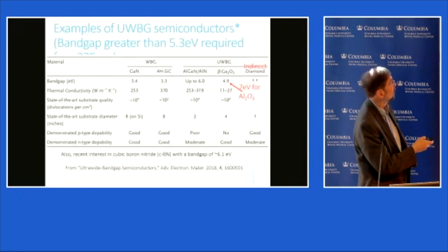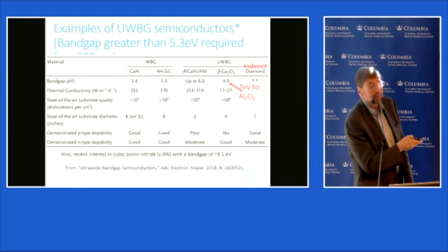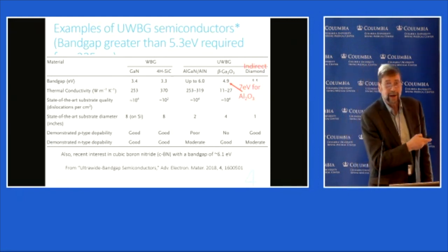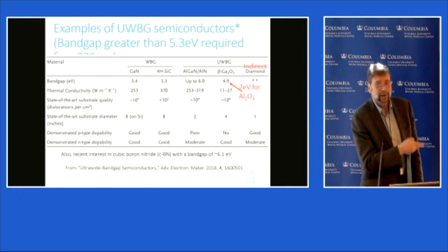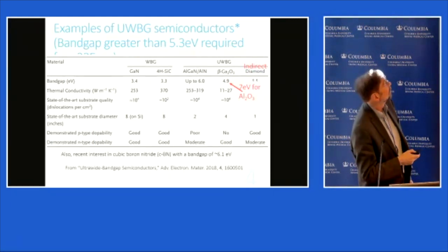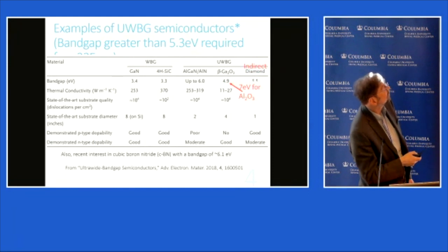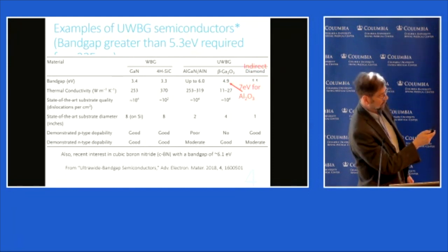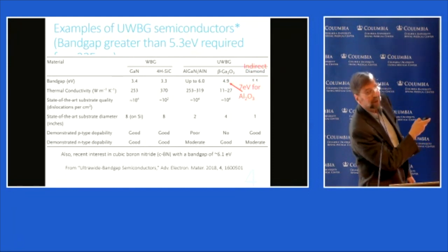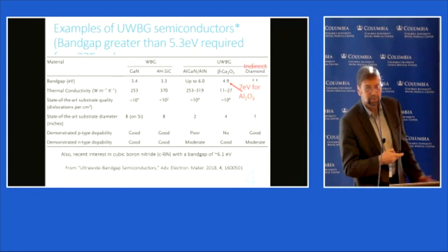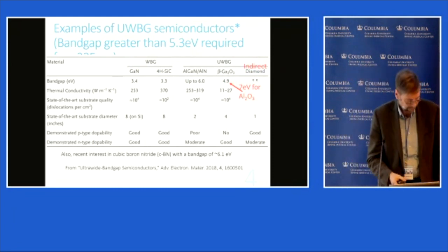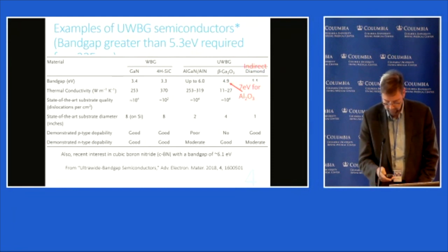recently come online. And it's interesting, but it's really got a lot of development to do before it starts to compete with the AlGaN system. And it's just tough with these other materials to get them up to the band gaps that you need. To get to this Far-UVC, you're talking about a band gap of 5.3 eV. That's big, okay? So it's something that's difficult to make work.